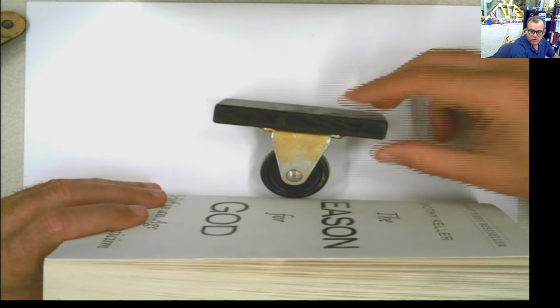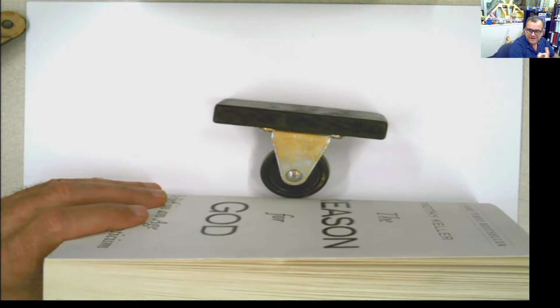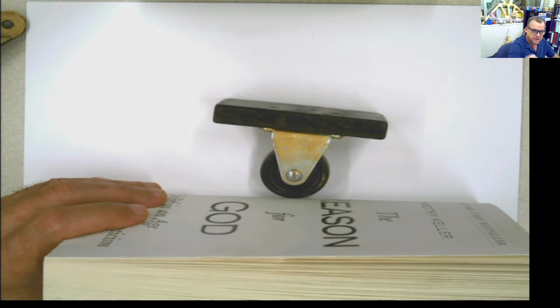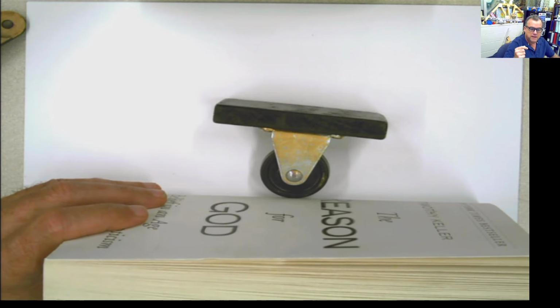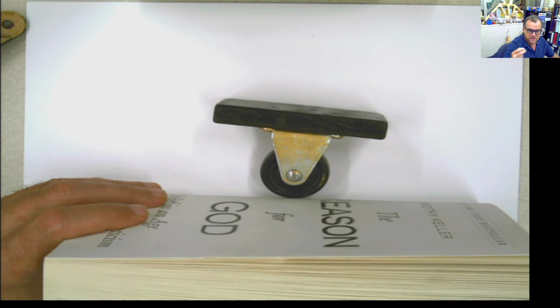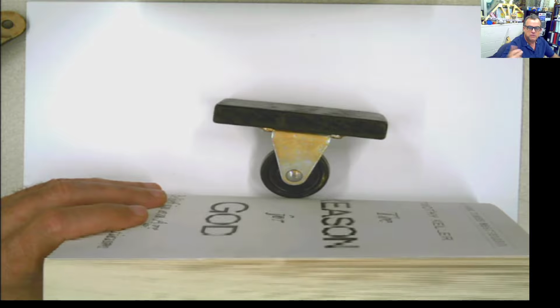Obviously it's rotating. So if it's rotating, there is not any restriction against moment, meaning the moment is free, and meaning the support cannot provide a moment. This is extremely important. Whenever you have a restriction in rotation, it's because a support reaction moment is provided. And whenever you have any type of translation restraint, it's because the support is providing a force in the opposite direction to the possible translation.